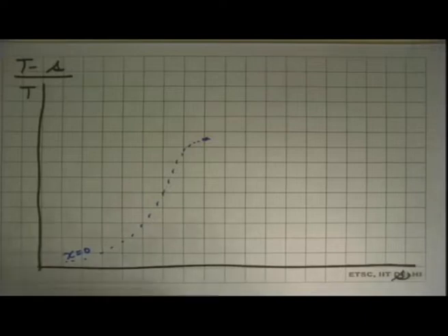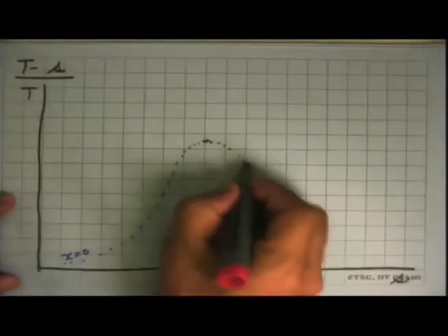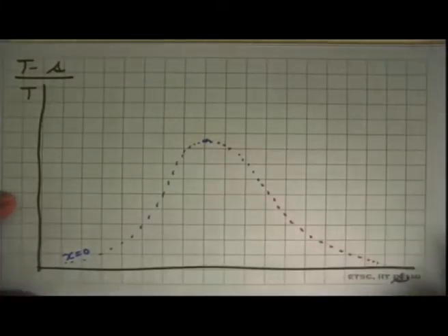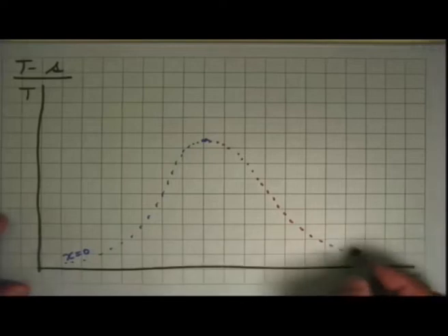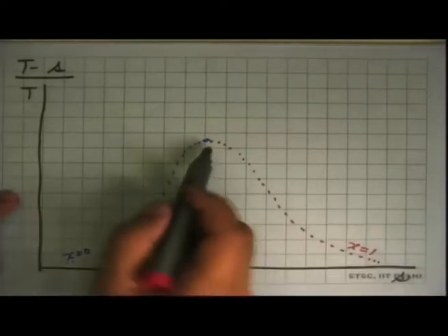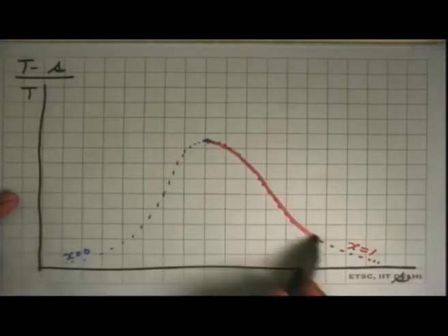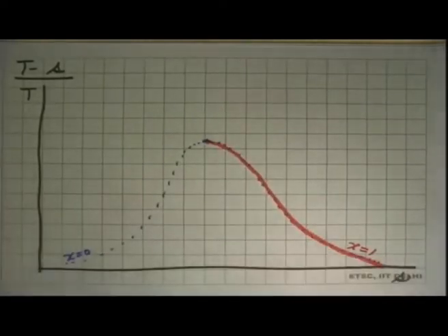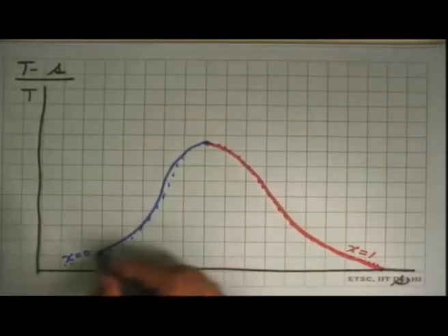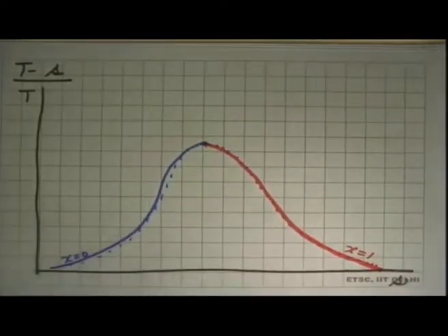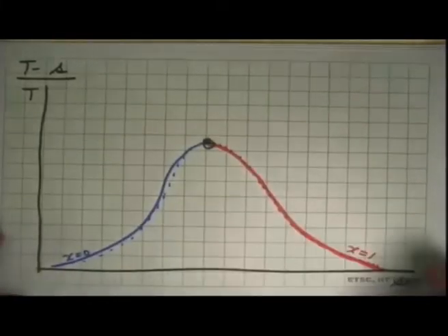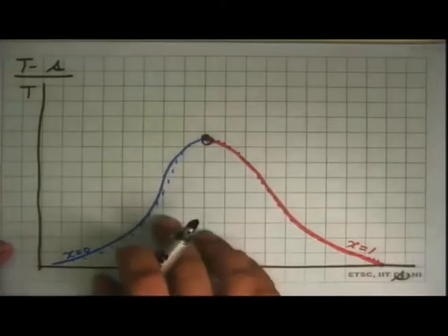And we continue the same plot. We take all the properties of the dry saturated vapor and make a plot, and it looks something like that. This is all x equal to 1, and we can join all of these. This is the saturated liquid line, and this side we get the saturated vapor line, and at the top is the critical point. So this is the dome again.